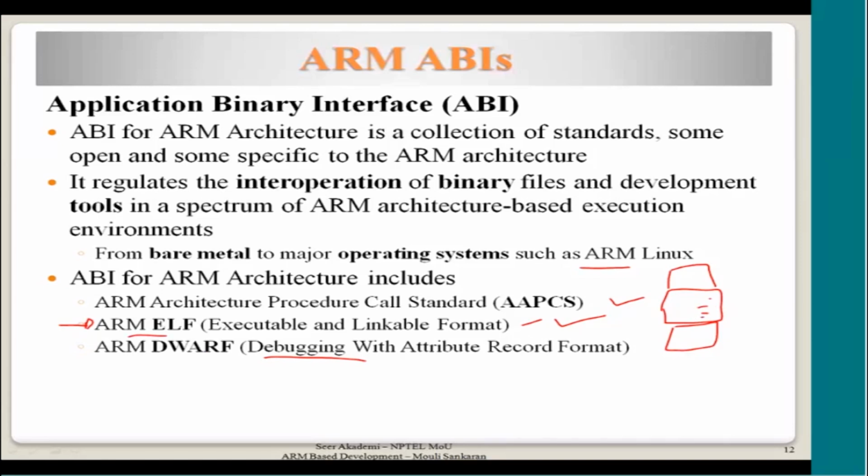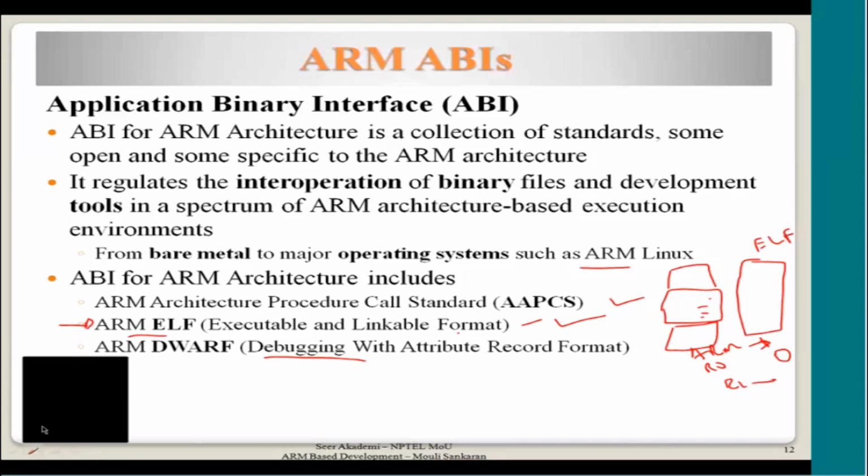Okay, so the ELF format is generic to any processor. It is not assuming any particular architecture, because the ELF format is common for any processor architecture. So ARM has to map to the ELF format. So it may say that, okay, my register R0 is mapped to some other register which is defined by ELF. My R1 is mapped to this. So this kind of register format specific to ARM is defined in this document, ARM ELF.